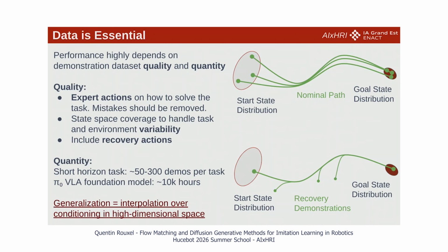When you do teleoperation and the recording, it takes a lot of effort and time, because you need to stop the robot, reset the environment, remove everything to go to the special case you want to demonstrate, start the recording again, do the recovery action, stop and start again. So this reset of the environment takes a lot of effort. But when you know what's going to fail, you can do it.